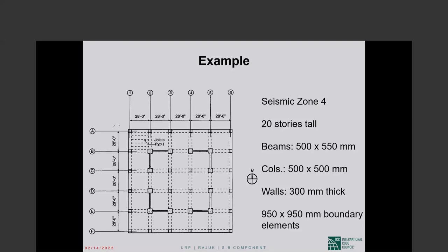Or you can try to provide ductility. Obviously, you will not comply with the special moment frame requirements, but you do that by wrapping from the outside. There are techniques, or you can do jacketing. You can build columns around the existing column in which you have ductile detailing built in. So there are ways of approaching it.